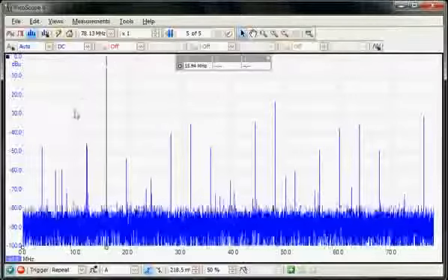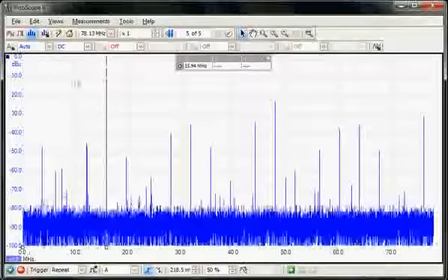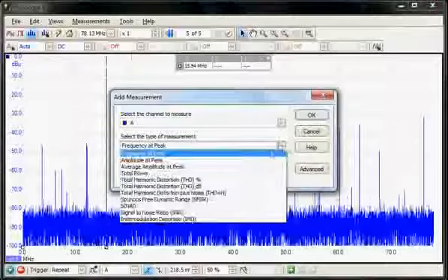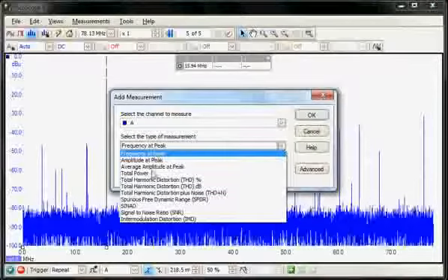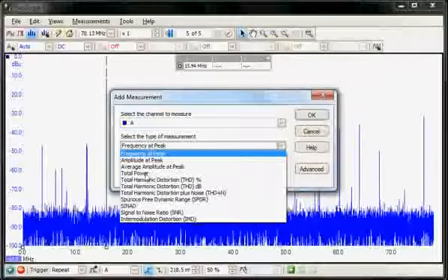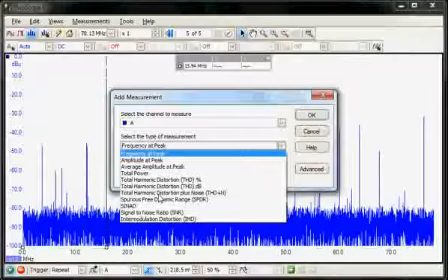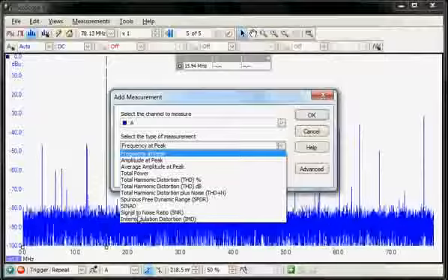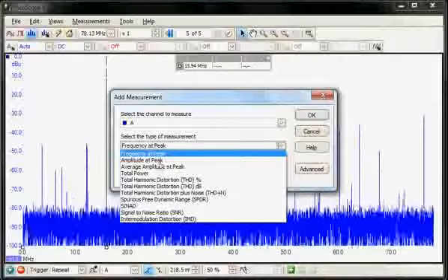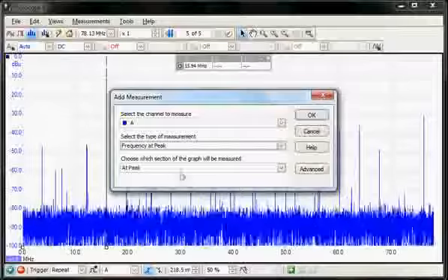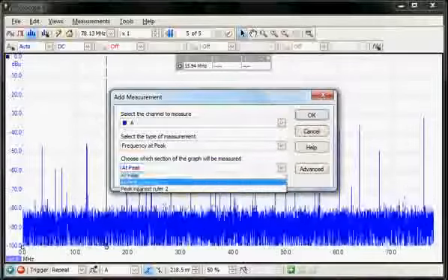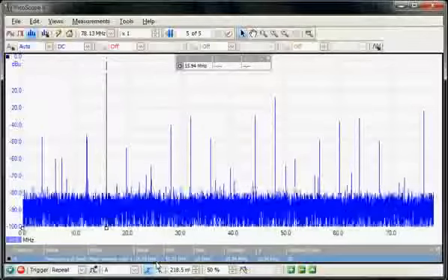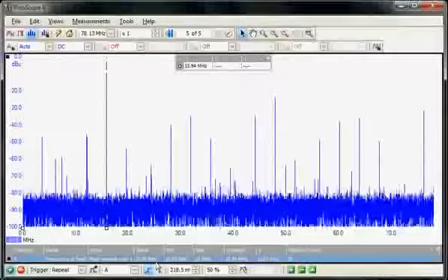So it's possible to measure a lot more of the frequency content of a signal in the spectrum display. We can perform these sort of measurements automatically by again using the measurements facility. In the measurements now we have the spectrum measurements, so we're measuring frequencies, average amplitude, power, total power, harmonic distortion, spurious free dynamic range, SINAD measurements, signal to noise, and intermod distortions. If we wanted to measure the frequency again of this particular signal, we measure it at the ruler, say. Okay. So here now we're doing an automatic measurement of the fundamental frequency, the 16 megahertz.